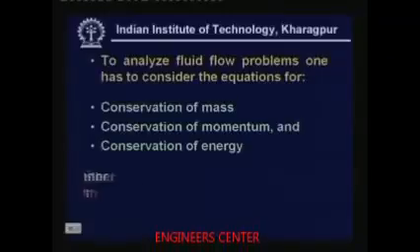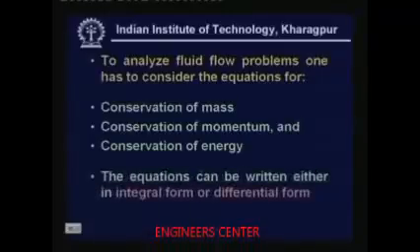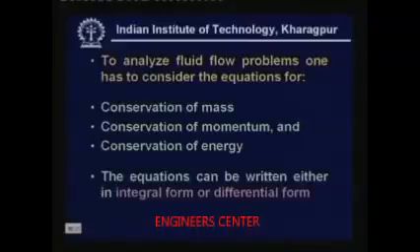Now, depending upon the approach, you can write these equations either in integral form or in differential form. That means, if you are taking a control volume and apply these conservation laws, you get integral form of equations, or if you take a differential element inside the control volume and apply the conservation laws, you get the governing equations in differential form. In the present lesson, I will give you only the integral forms of conservation of mass and conservation of momentum.